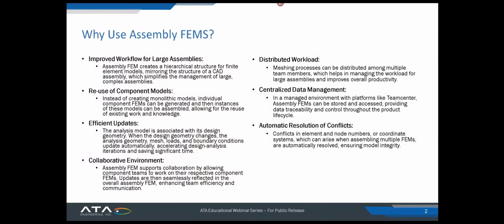Being able to reuse component models. This is one of the ones we're really going to focus on today, and really where AFEMs shine is being able to, say you have repeating components within your assembly. All you need to do is mesh just one iteration of that component, and then the assembly FEM will map that individual FEM iteration to all of the locations throughout the assembly. So really useful feature there.